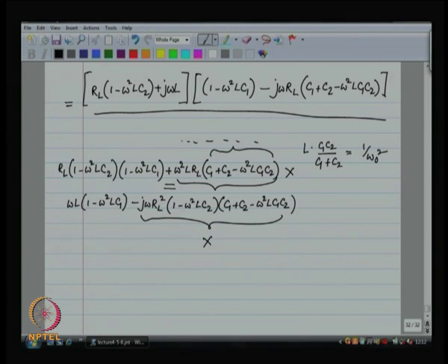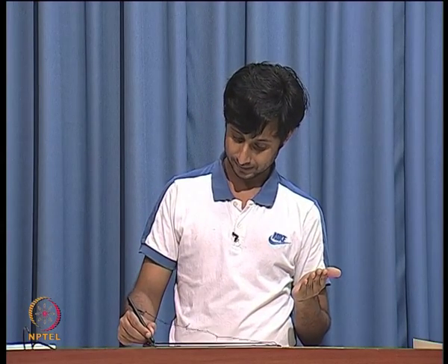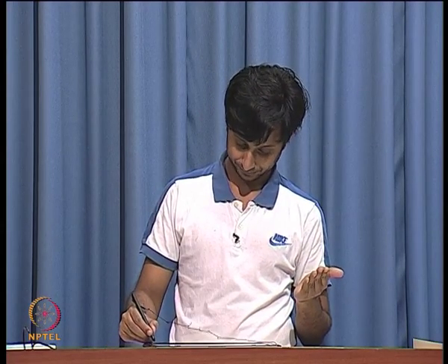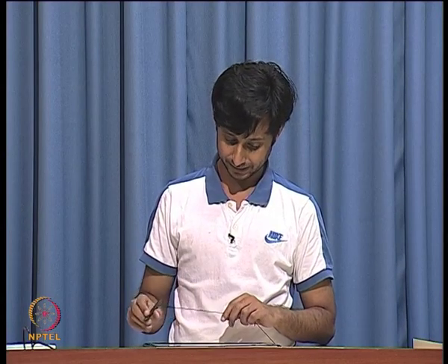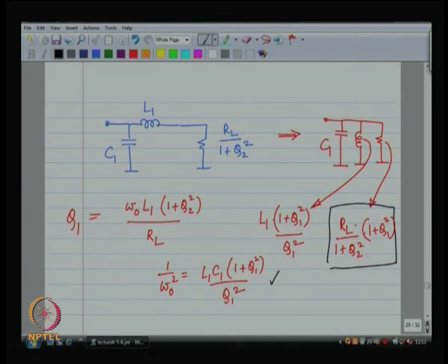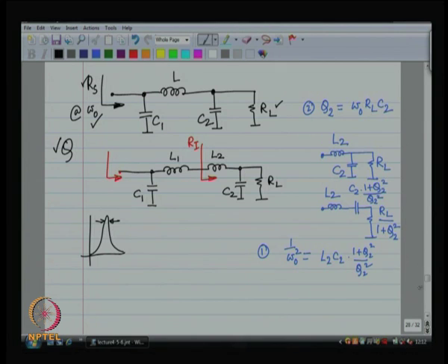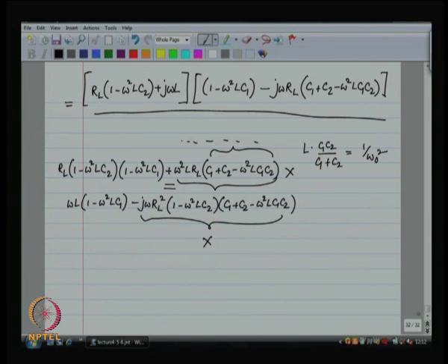We like being engineers. So, we make a lot of these approximations. First of all, the big approximation here is that L1 does not really resonate with C1, L2 does not really resonate with C2. What resonates are a little different. These are actually my equations, but we assumed that Q is large. Okay. So, we made that engineering approximation first.